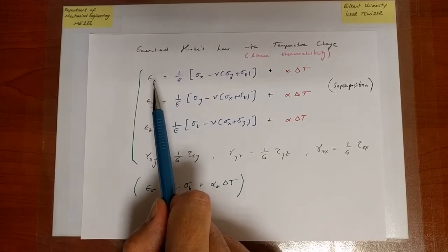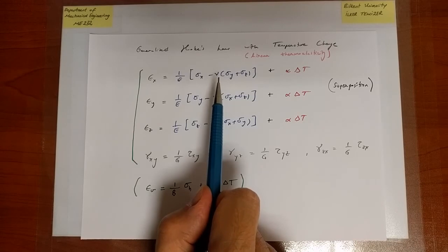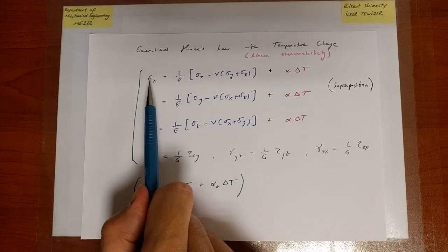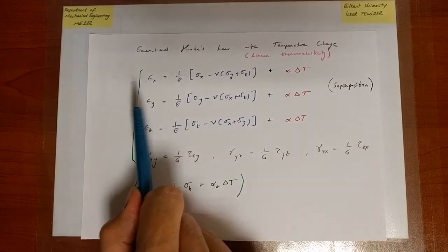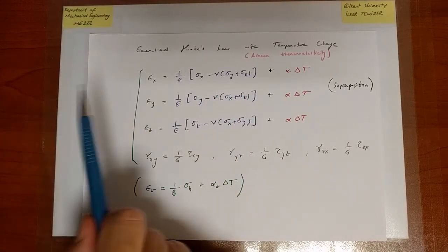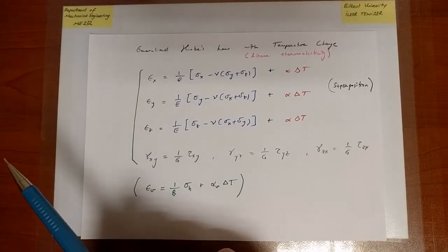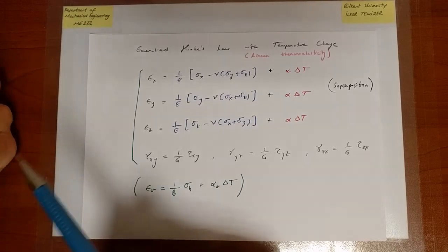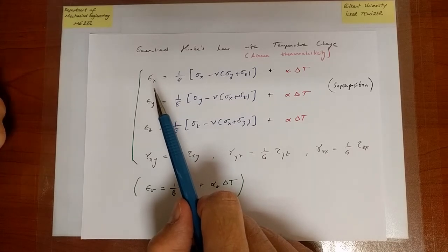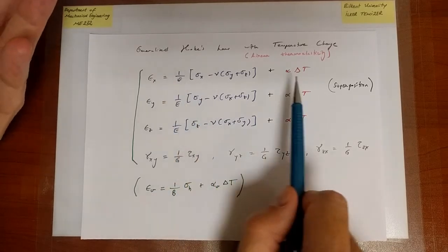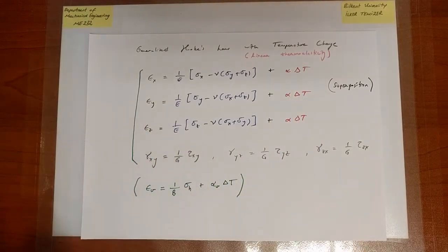Or conversely, the second point is, if you have 0 stress, it doesn't mean that you get 0 strain. And we've already observed that, because if you change the temperature despite the fact that you have 0 stress, then you can still get a certain amount of strain. So in other words, this is a relation that is always going to work. And from now on, right, so 1, sigma is not anymore E times epsilon. There are other contributions here. And 2, sigma is not E epsilon even in 1D, because there could be a temperature change which induces a certain amount of strain as well.